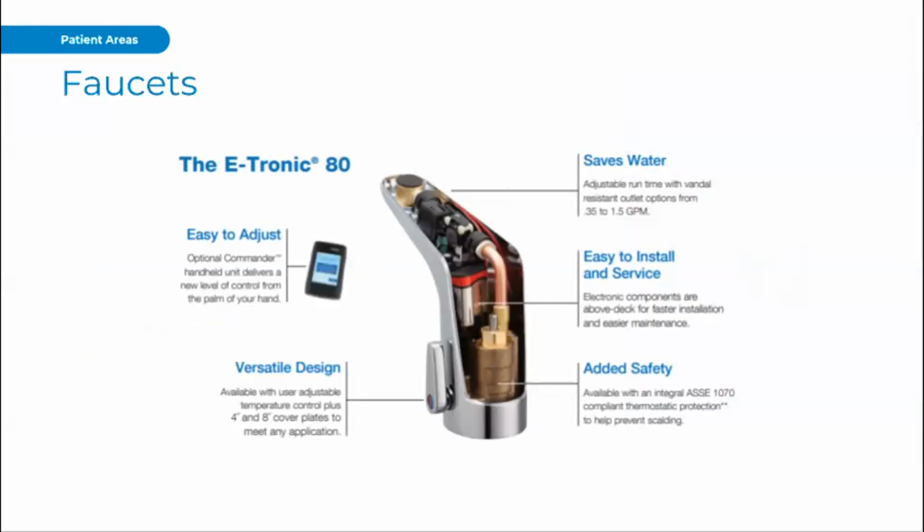More and more, we are seeing this trend towards above deck servicing, the ability to just pop off the top and access your solenoid or access the 1070 compliant thermostatic mixing valve, as we noted. With this model, you can use what they call the commander unit to adjust the temperature and help with your installation. It'll help you set your sensor range, and it'll also give tracking information. Say you're using a battery model. There's a variety of manufacturers that have some sort of usage tracking, so you know when those batteries might need to be replaced.